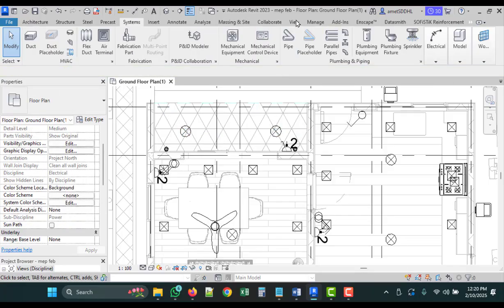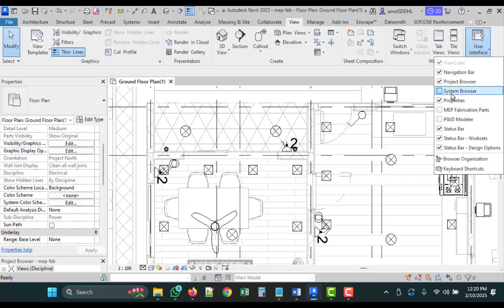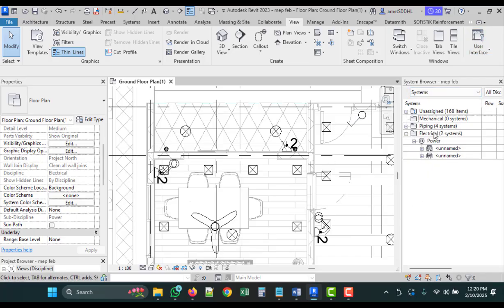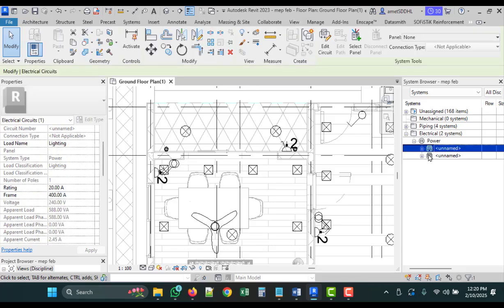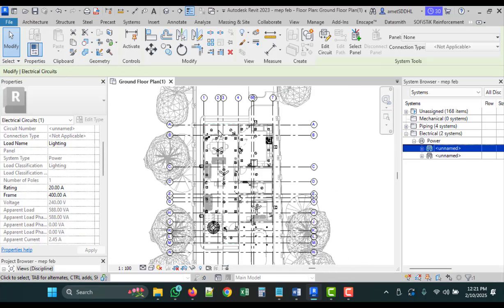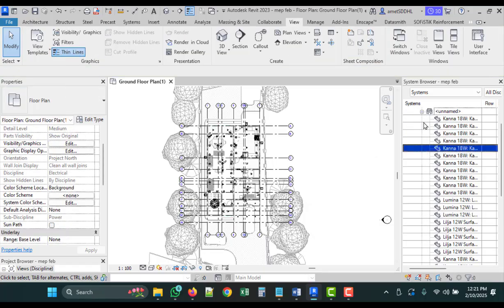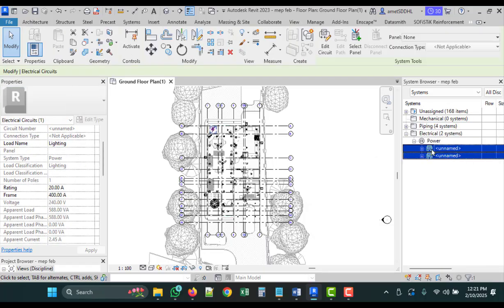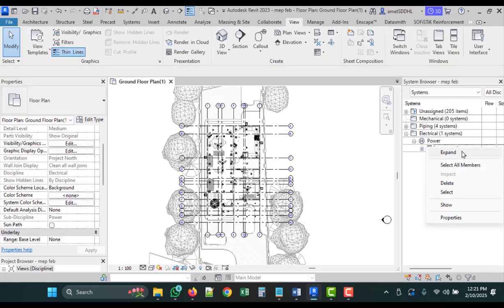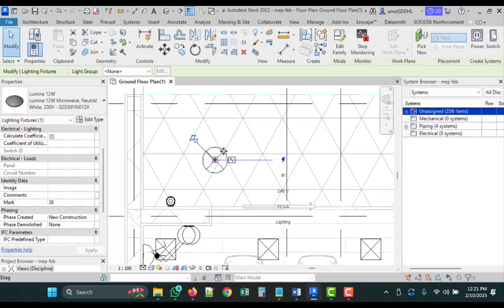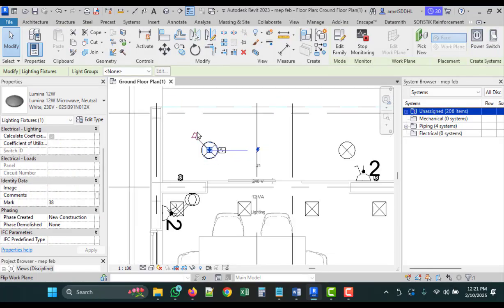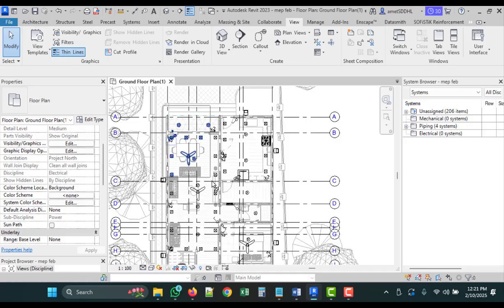To resolve that, we'll go to the systems browser and then we'll go to the electrical side. In this system, I had created two which I had cancelled, hence that issue. If I select this, you see that this is referred to this one, and there's another one here as well. So what we'll simply do is just right click and delete the system. By deleting the system, we don't have any systems existing again. So now we have all the power back. So let's go ahead now and add it again.